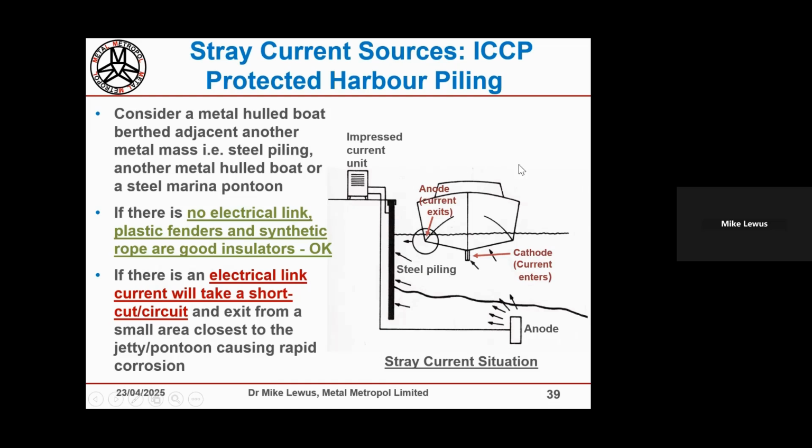If there's an electrical connection between the boat and dockside power, there's a risk that the ionic current that the anodes are generating looks for a short circuit path and passes through parts on the boat. If it's isolated and there's no electrical link, that's okay. So it's another reason to consider, in some circumstances, using a galvanic isolator or an isolation transformer.